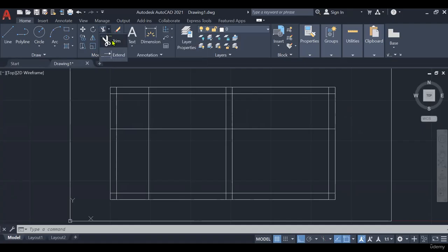We just go to the trim command. I press enter on the trim command, and I just trim this one, this one, this one, whatever the extra parts are there. Here in the corners also we need to delete this one. Why do we need to delete this one? While showing the plans, it should look like a whole single plan.